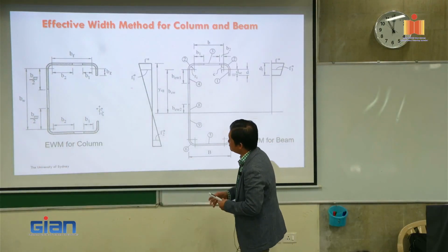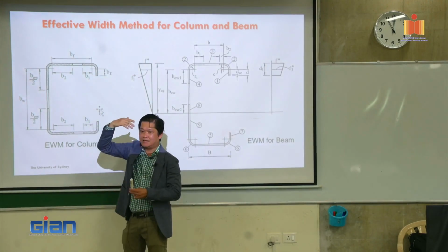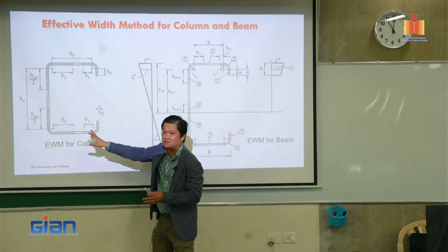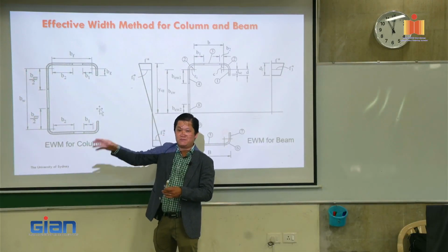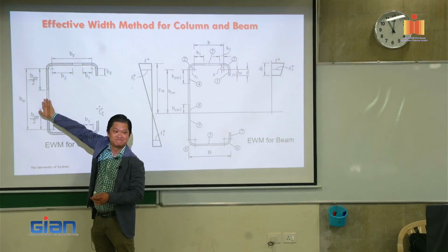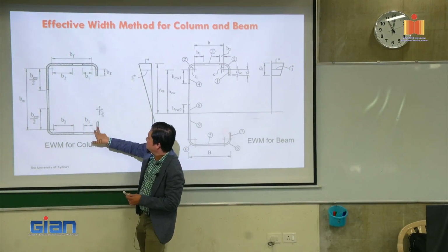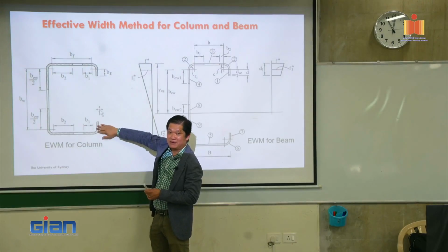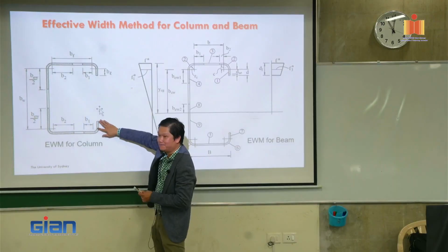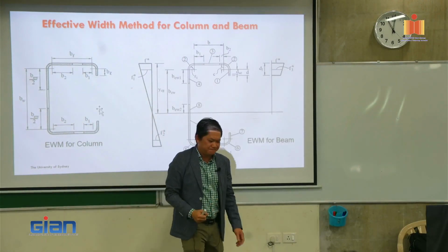Then we calculate each element, then we can come up with the design equation. So for columns, you can see that because of the thinness of the section, the whole section is not effective. So it means that, looking back at what we learned, there's some area that we need to remove. Okay, so that's the area that we need to remove. This one looks like there's no missing part in here because when you calculate, this is fully effective. All right, so the lip is good. Then we need to calculate here, it is good. Now, that's it for column.